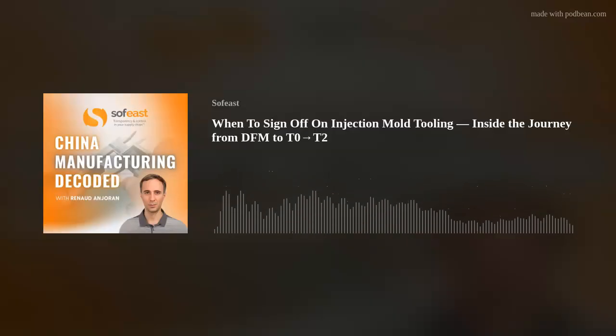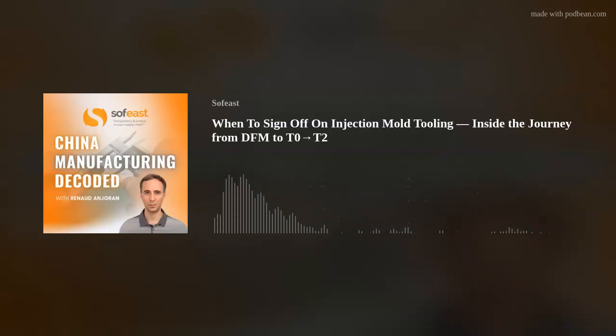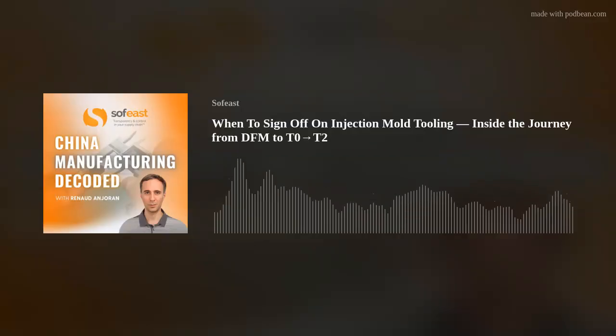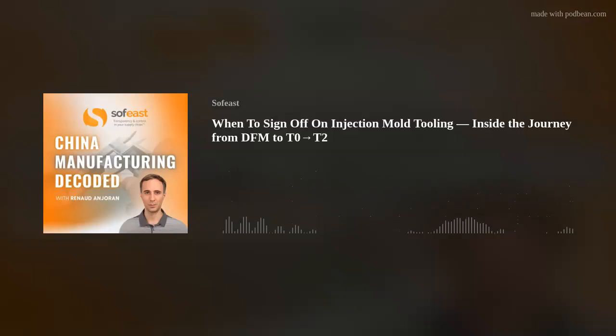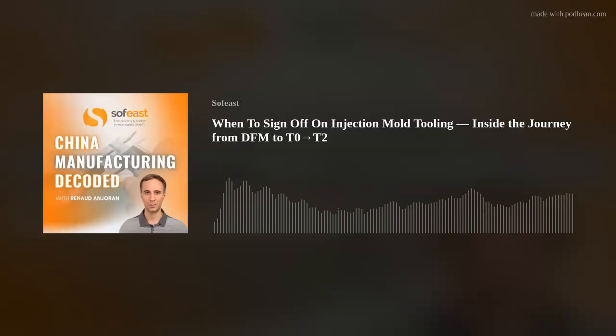Now, this is where things start to get a little bit interesting, and some customers get a bit lost at this particular stage. They think that, because the tool's finished, we should go straight into mass production, which is not necessarily the case. Initially, we will do what we call a T0 or a trial run. The T0 means we are going to load that brand new injection mold tool into an injection mold machine, and we're going to run it for the first time.